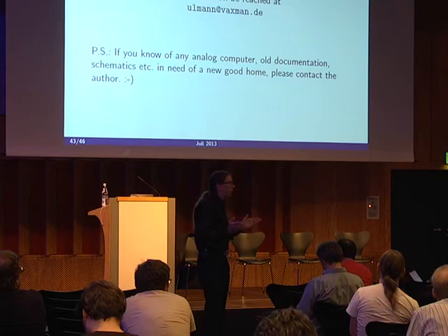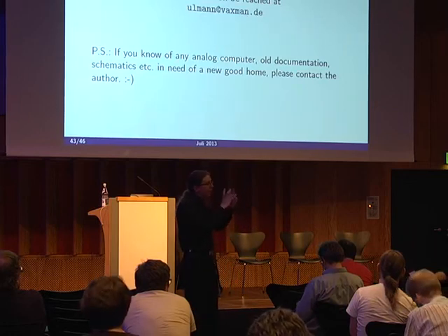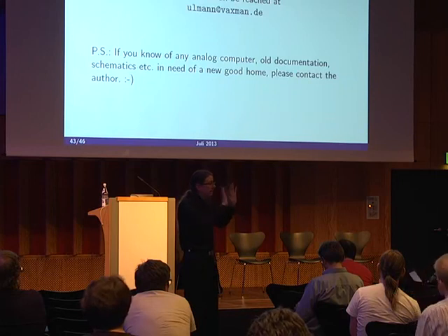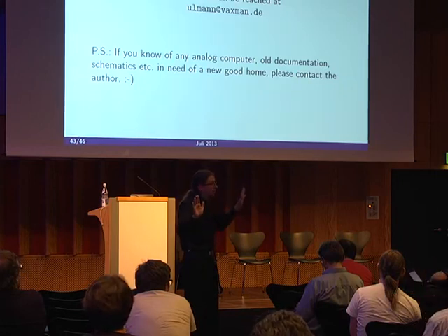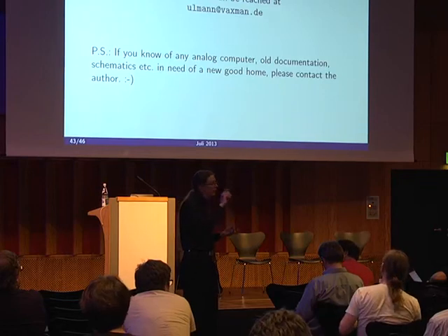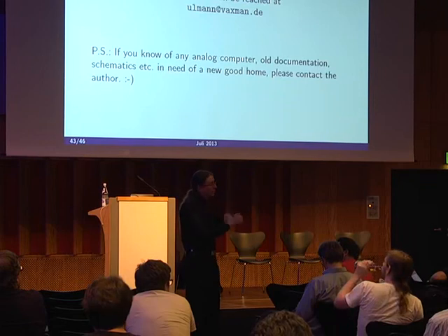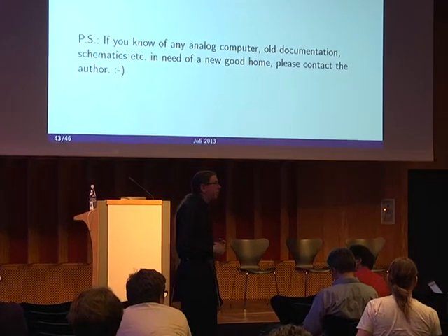A modern implementation could look like an FPGA with multiplexers interconnecting some macro blocks containing the integrators and various computing elements, and you would change the structure by just feeding the multiplexers with the correct bit patterns for selecting the proper input lines and routing signals to the proper output lines.